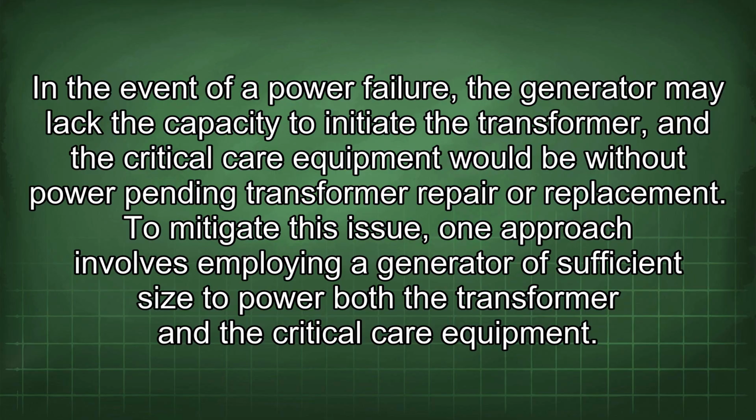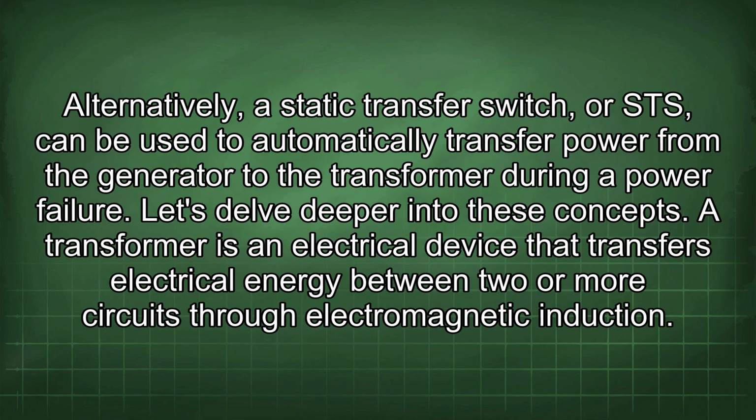To mitigate this issue, one approach involves employing a generator of sufficient size to power both the transformer and the critical care equipment. Alternatively, a static transfer switch, or STS, can be used to automatically transfer power from the generator to the transformer during a power failure. Let's delve deeper into these concepts.